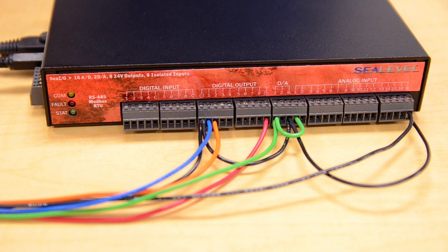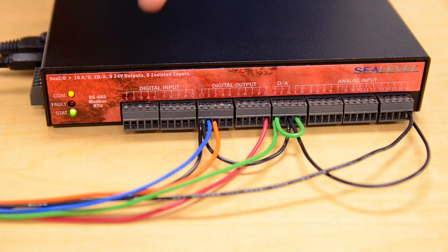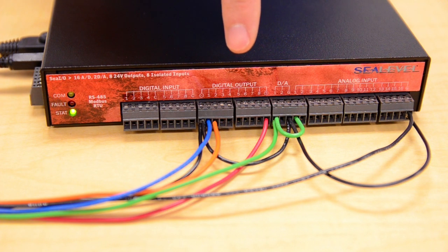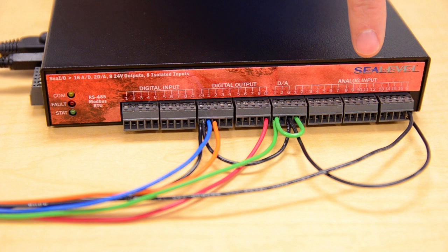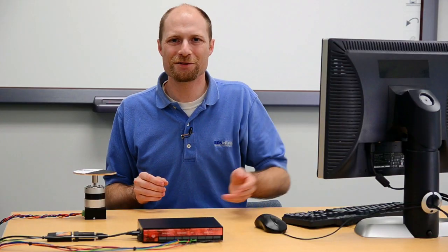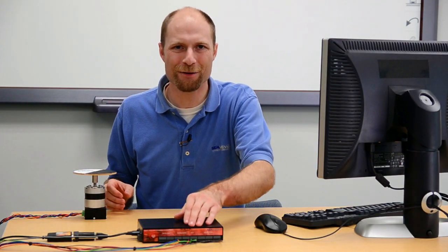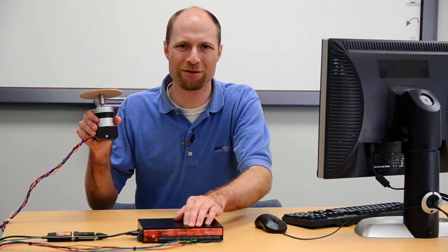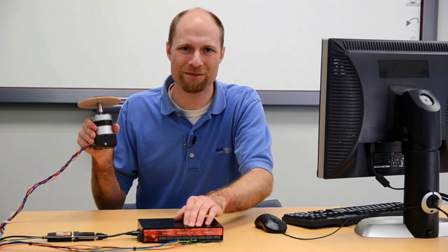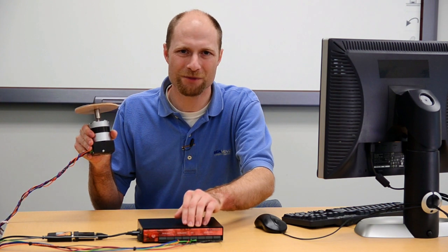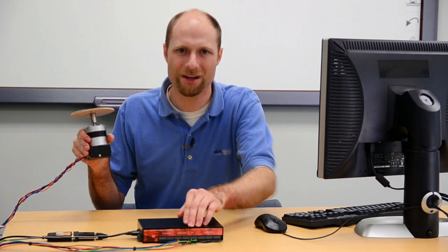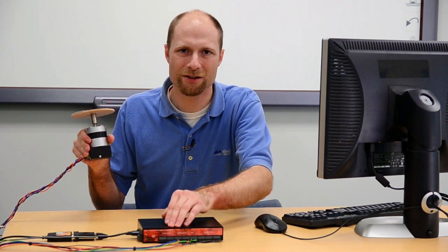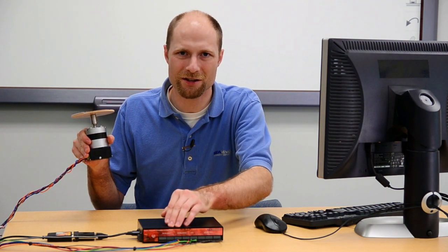The 470 module is a multifunction I/O adapter that supplies 8 isolated digital inputs, 8 open collector digital outputs, 2 analog outputs, and 16 analog inputs. I used a 24-volt DC supply to power the CIO module and a motor with integrated controller from Anaheim Automation. I used an analog output to control the motor's speed and an analog input to track the control voltage. I used open collector outputs to control the brake and change the direction of the motor.